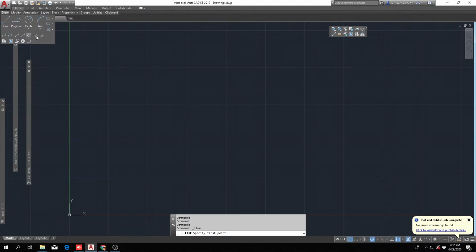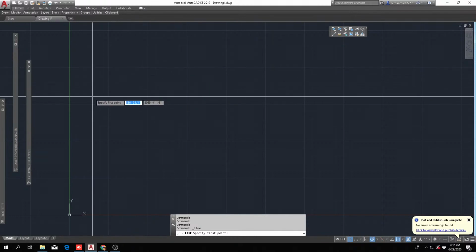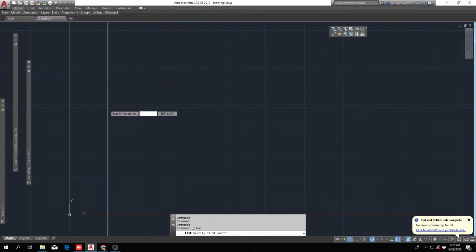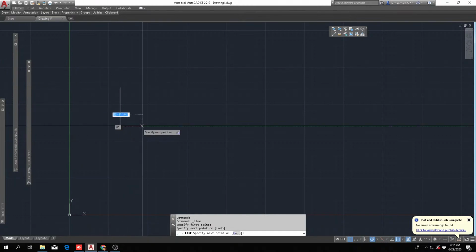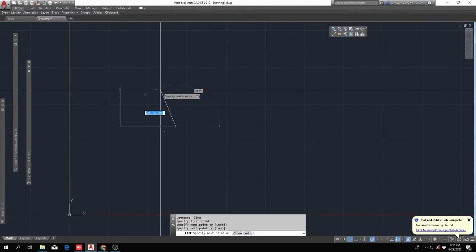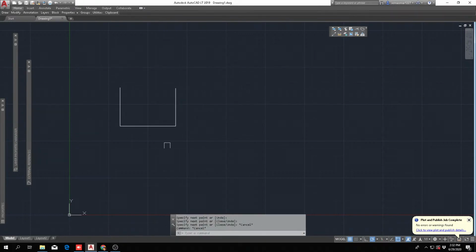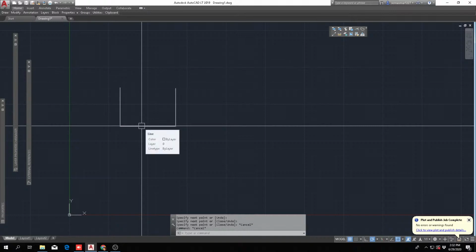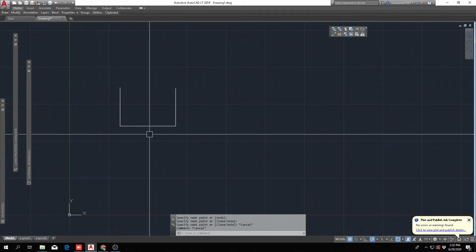And once you click line with your left mouse button, your command is already set up in your AutoCAD, and then all you need to do is just click anywhere, and as you can see there, you can put the line wherever you want. At this time, I'm not giving any dimensions. I'm just letting you know how the line command works. Okay. Later on, I'm going to tell you, give it 20 feet of line or whatever, and I'm going to teach you all of that. Okay, so I just want you to get familiar with the tools. So that was the first command, line.